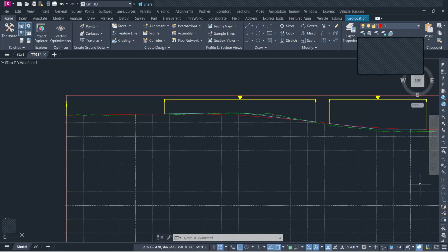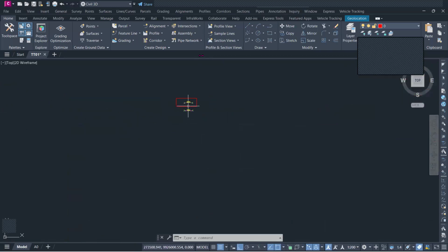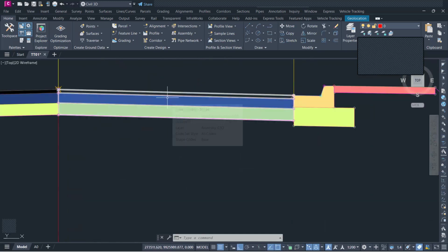for our works, okay? We have also talked about the major important thing in roadworks, that is cut and fill quantities. And then after cut and fill, we have the pavement layers. So the various pavement layers that you developed in your design using the road assembly. I expected you people to have drafted something. So for example, these are the road pavement layers. So you need also to generate quantities for these pavement layers.